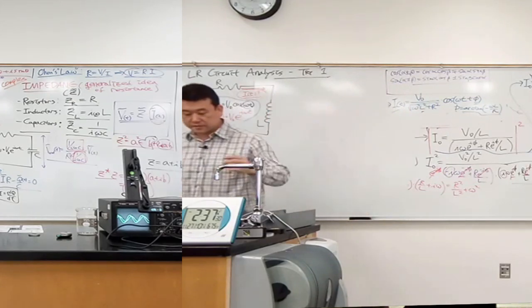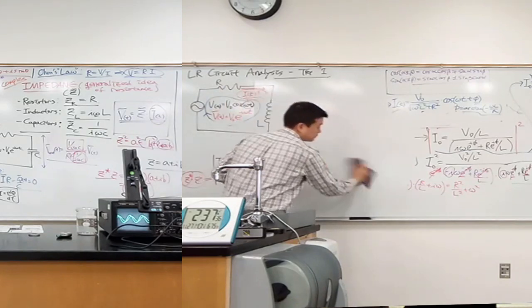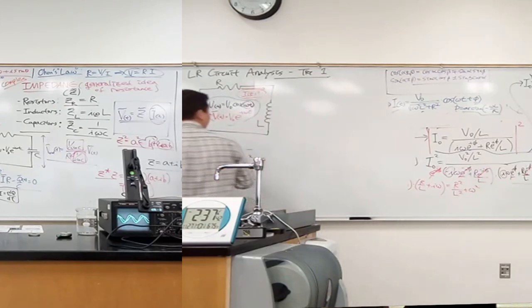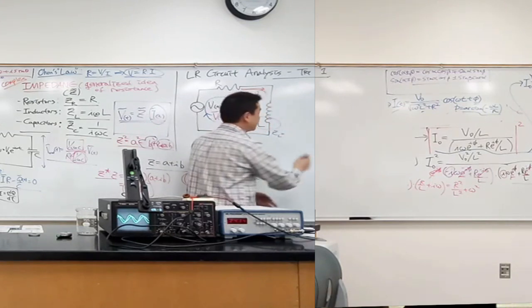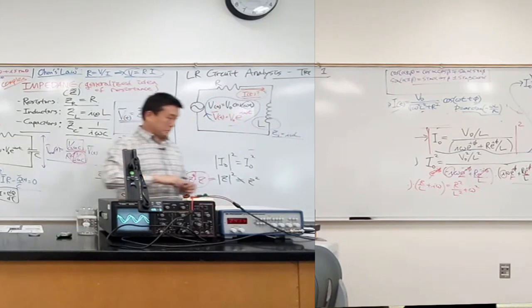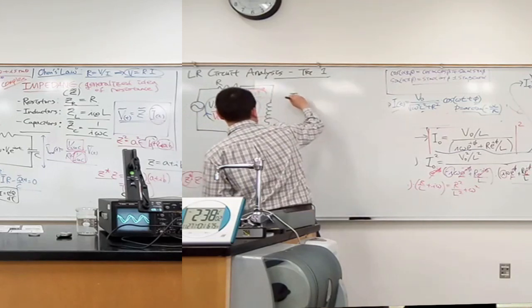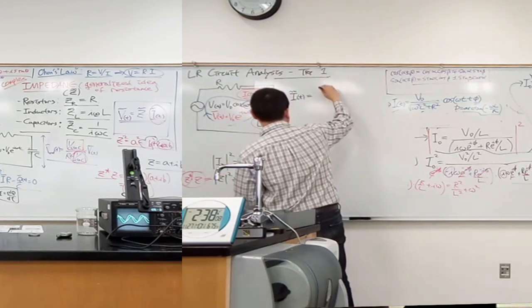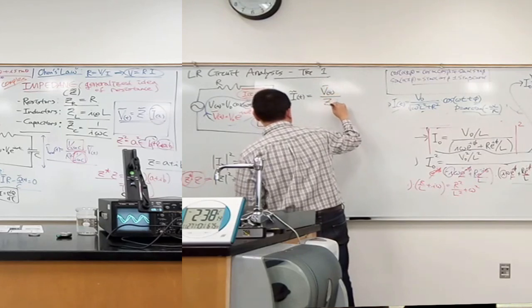with these complex impedances, you work out the circuit problem like these were resistors. Even though an inductor is not a resistor, you treat the inductor like a resistor with a resistance, I omega L. That's the impedance of the inductor. So let me write it out. The current that's going through the circuit should be the voltage divided by the equivalent impedance.